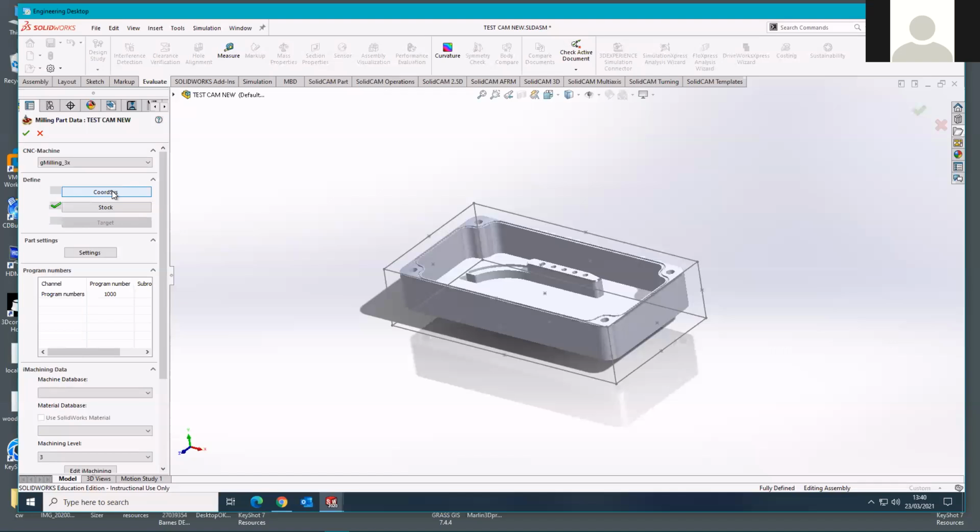And the CNC machines work exactly the same. So we have to decide now, where are we going to put that 0 point? Where are we going to put the part coordinate system? On these sort of one-off jobs, I like to place it on a corner of the stock material, because that's quite easy when you're running the CNC machine.